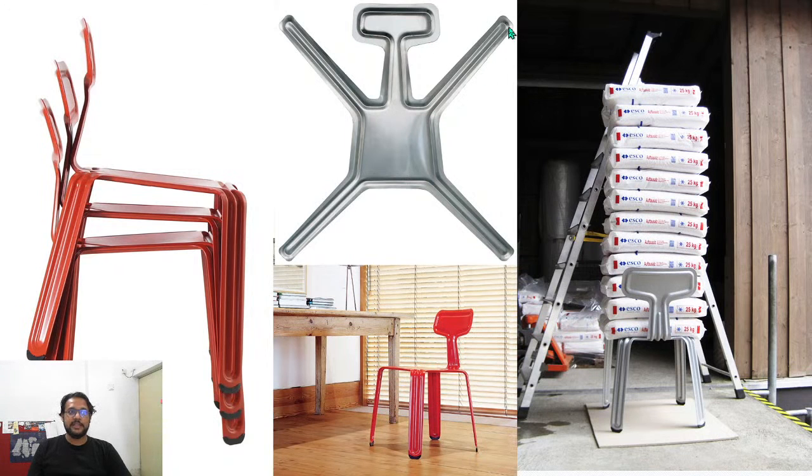You can see this is the layout of the sheet metal. First, you take a sheet metal, you give this kind of a groove to it, you form it, right? And this operation imparts a certain amount of strength to these flat surfaces. Now when you bend it, it looks so simple and so fragile, but look at this.